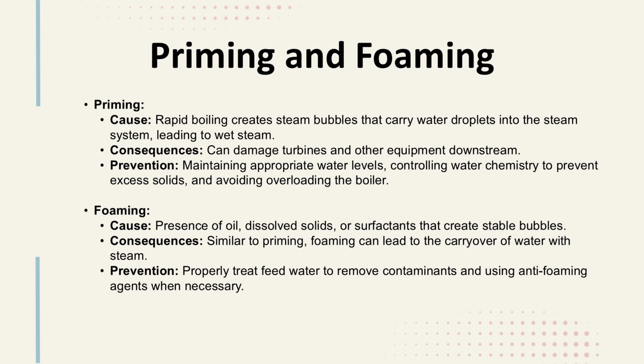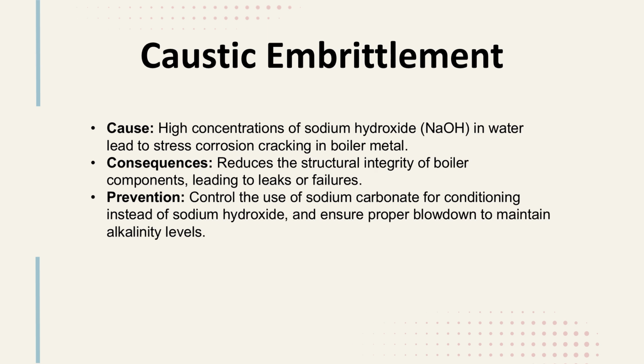Next up is the issue of caustic embrittlement, a specific type of corrosion caused by high concentrations of sodium hydroxide, NaOH, in boiler water. This phenomenon leads to stress corrosion cracking in the metal components of the boiler.